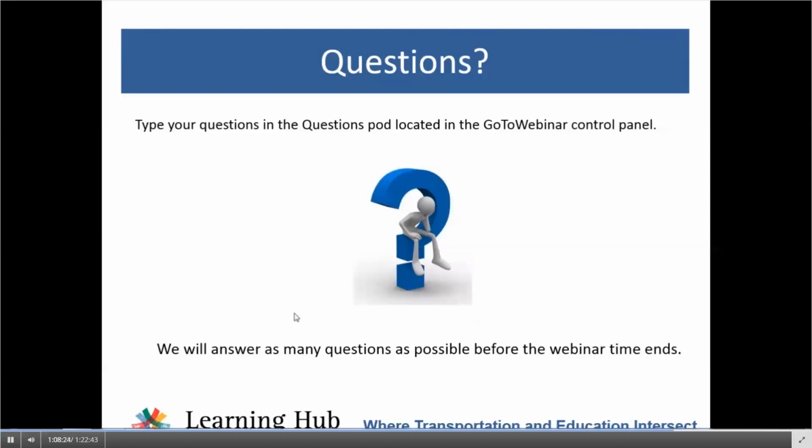Okay. The next question is: is the spreadsheet freeway planning tool applicable to locations where we have multiple hours of LOS F? The spreadsheet tool is really designed for a 1 hour evaluation. You can certainly extend it to look at multiple hours. Keep in mind that if you have multiple hours at level of service F, you're going to have a lot of queue spillback issues.